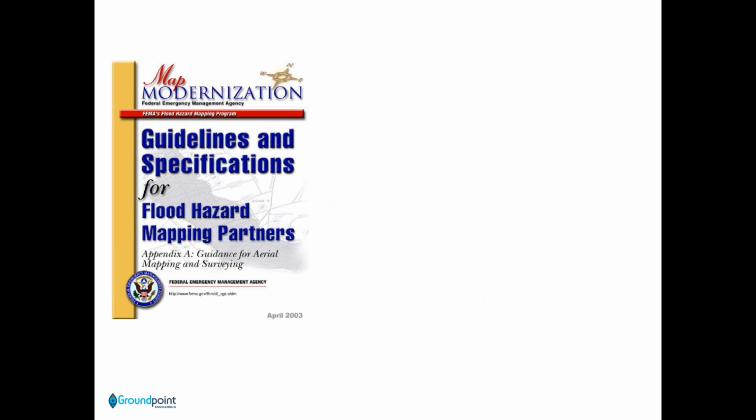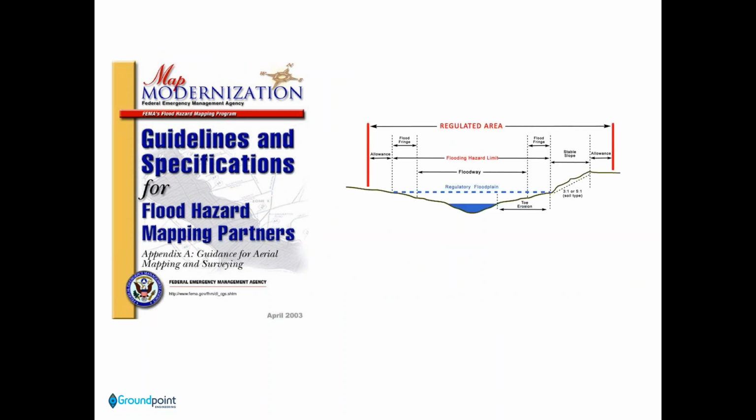So the focus back in those Appendix A days of LiDAR was really on the floodplain itself, both in cross-section and in profile, and establishing whether LiDAR data could really adequately characterize the physical world. The gold standard was FEMA 2-foot contours, right? LiDAR data typically had a post spacing of about 1 meter and a vertical accuracy of about 6 inches.